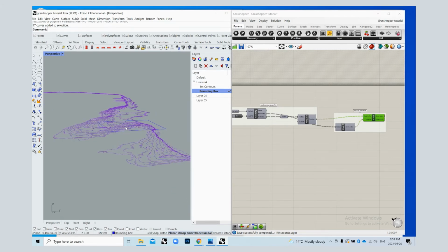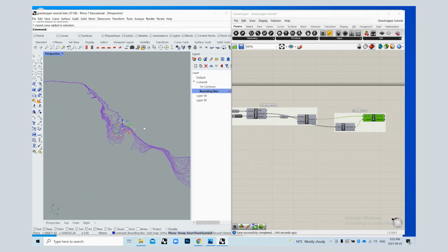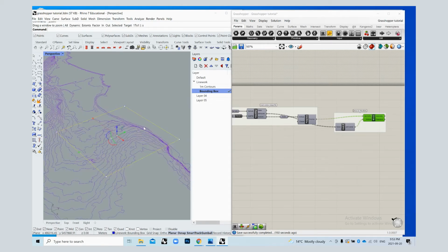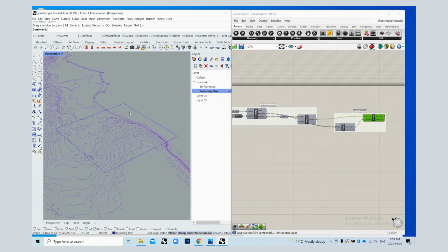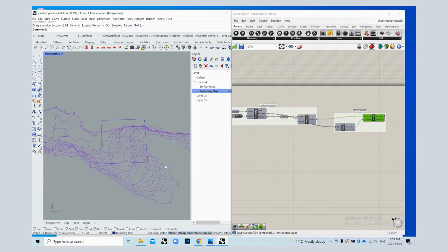My scroll is getting a little bit messed up and is kind of finicky to scroll around with. So I'm just going to click this bounding box and type Z for zoom and S for selected, to refresh the view, zooming in to this bounding box area. So let's trim off the excess fat, shall we?